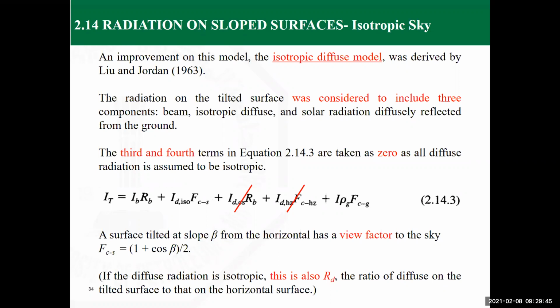But talking about the circumsolar disk alone or the horizontal components, this contribution has been considered in the isotropic condition. Isotropic again means it is independent of the direction. Because it's independent of direction, there's no point in considering different components or further components. Accordingly, term number 3 and term number 4 from the equation are going to be neglected, and we are only going to consider terms 1, 2, and 5. So this is what's called the isotropic sky model or isotropic diffuse approximation of the equation.